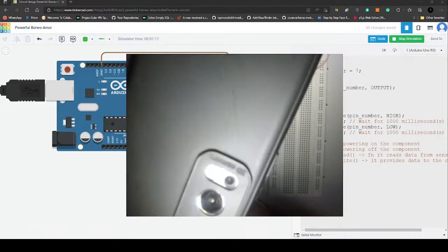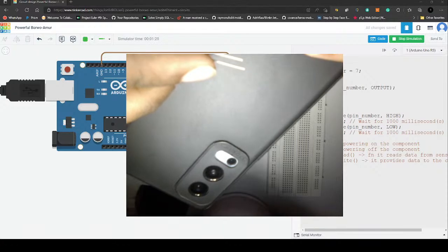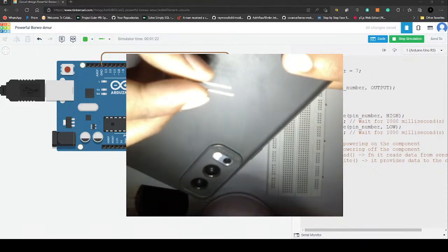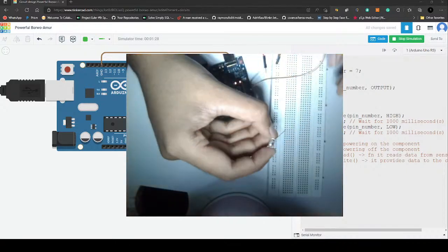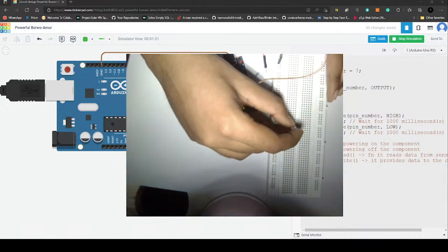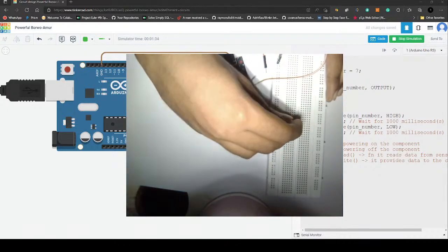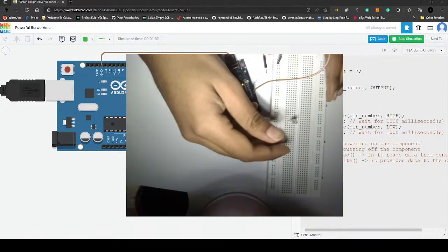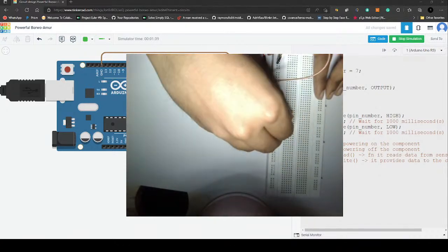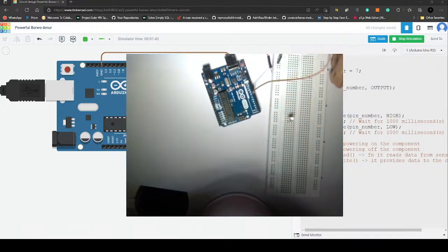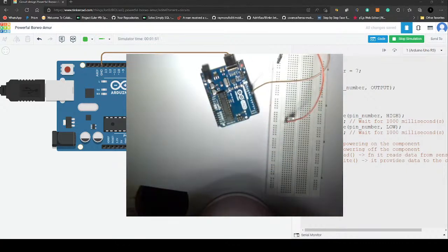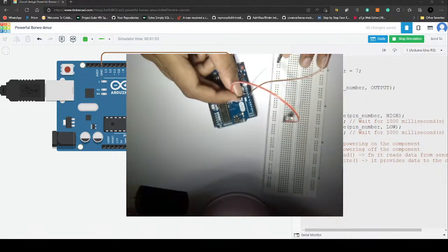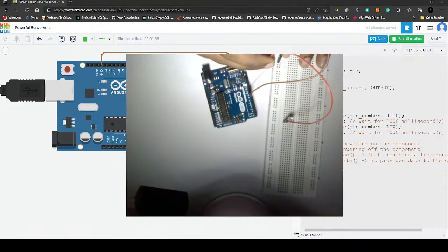As discussed before, the longer pin is the plus one. The longer pin is plus and the shorter one is minus. So you need to remember where we are plugging the longer pin. The longer pin is on the left side. So just put the LED up, like this. Longer pin is above. Okay. Take a connection from the longer pin to the pin from which we will deliver the power.